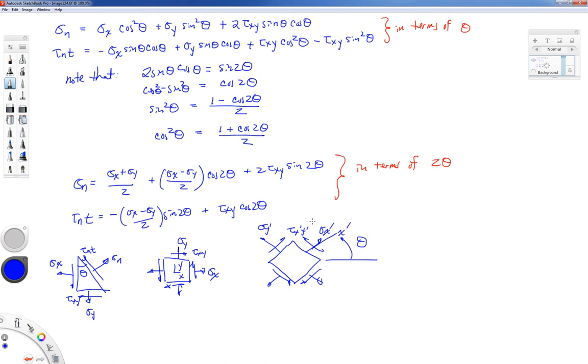That's called the stress on the orthogonal face. What is meant by that is it's the stress that's perpendicular to the x prime direction, which we can show on this block, but we can't really show on this block where we have sigma n and tau nt. So it would be the stress, I guess, sigma t, the normal stress that acts on a face that's perpendicular to the t direction. We call that sigma y prime.